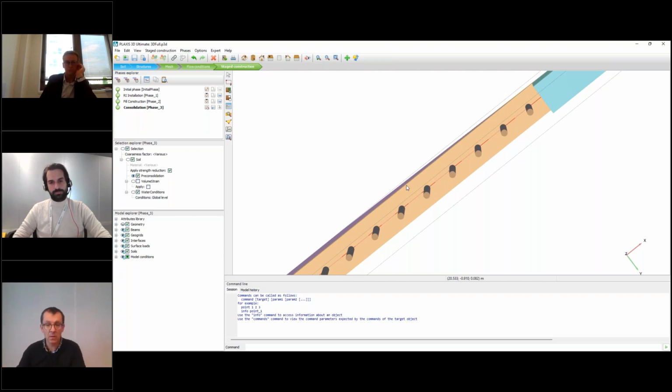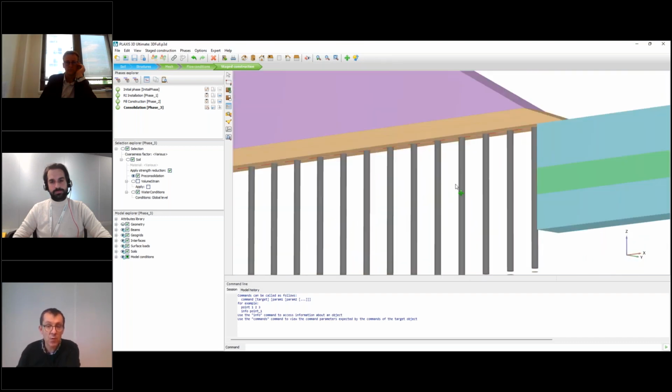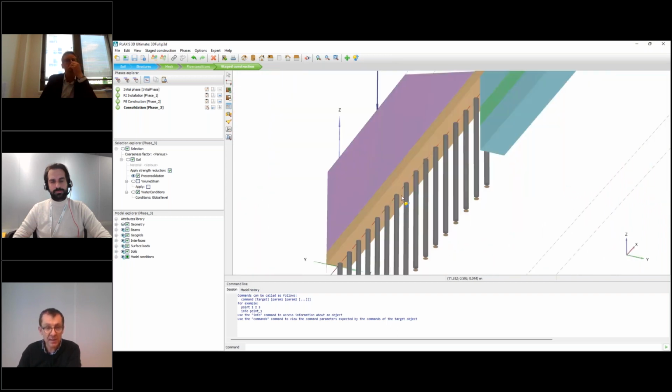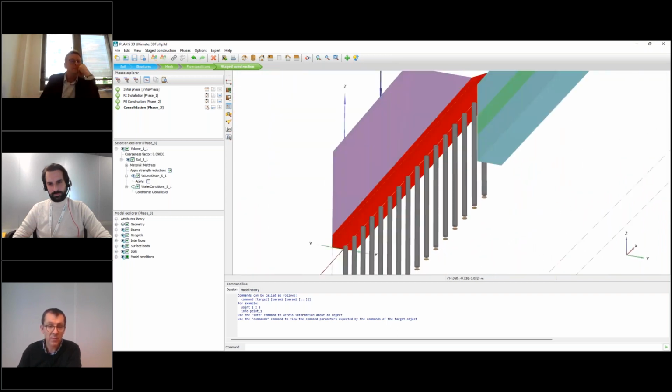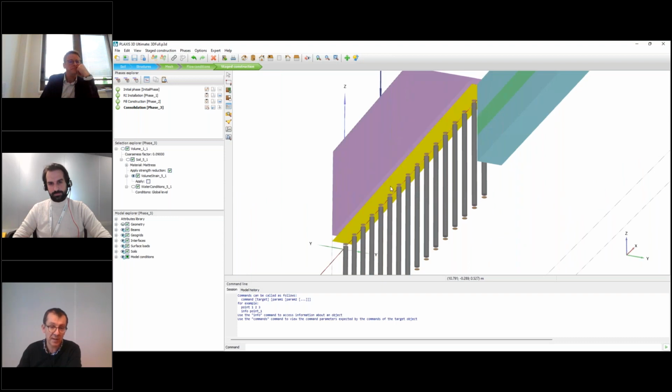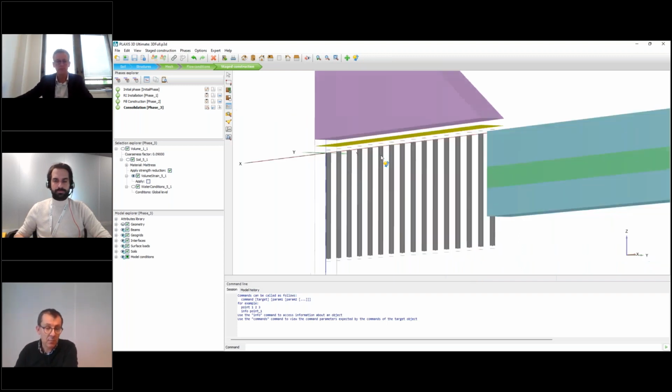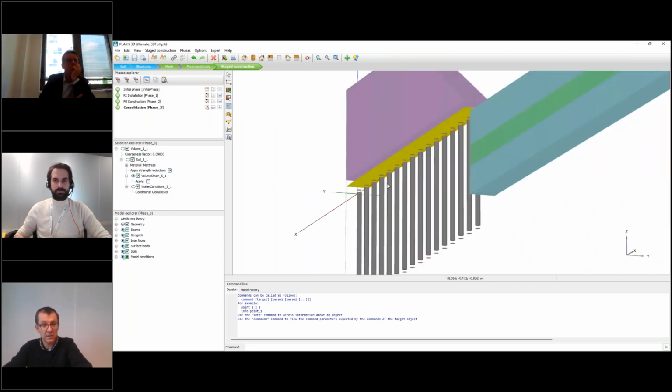So that's the model. The rigid inclusion is physically properly modeled using volumes and filled with the proper material. You see this type of model as well, with the consideration here of a geotextile. We could also have steel meshes, it depends, but the platform can ultimately represent in the most accurate sense how the load transfer may operate between the embankment and the rigid inclusion.